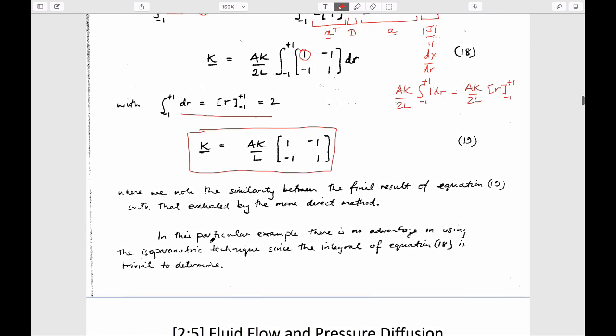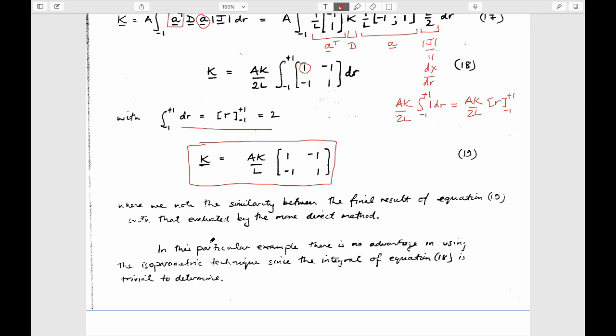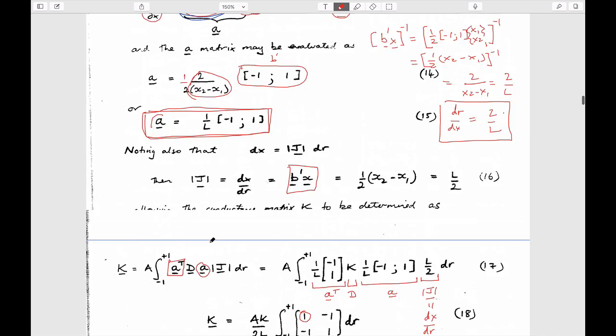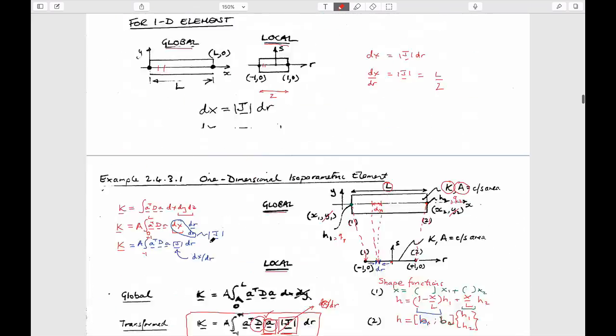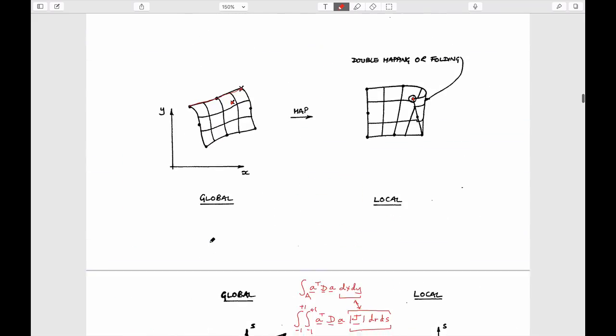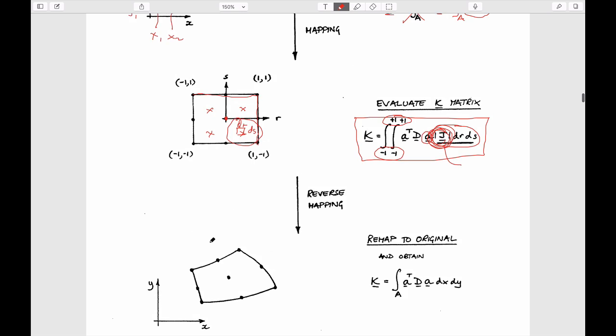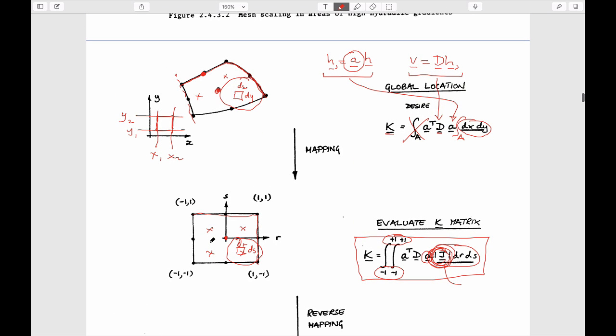And so that's basically isoparametric elements. So the big picture, I think, hopefully you can see it. It's always good to look at these things with broad brushes. The big picture is this, that we want to be able to figure out exactly what the conductance matrix is. We have a complicated geometry, not so complicated in our case, it's the same element. And we have more than a single node, say, per element.